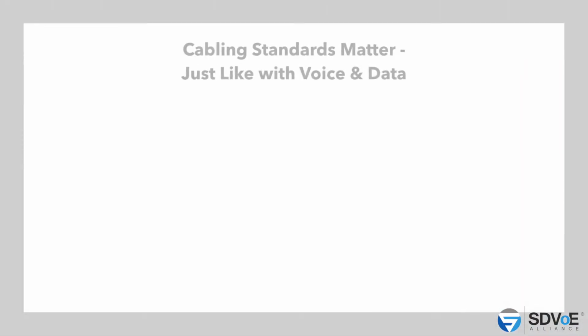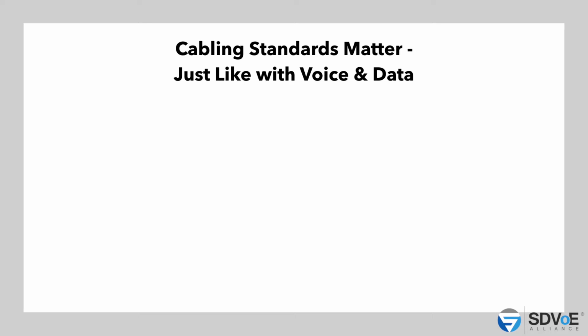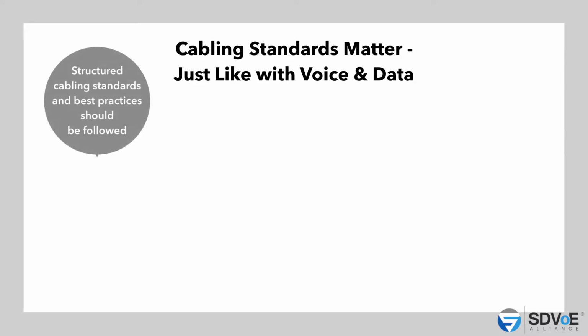So cabling standards. HDBaseT has really got its own standard, but if we start looking at the networking world and we start thinking about voice and data and any other type of application that we're now able to deliver over a cabling system, we're actually governed by technical standards. So in Europe we have EN 50174. It's a generic cabling standard that every cable installer fully understands. We've also then got our local country codes, and then we've got our international codes. So these actually tell us how we're going to design, how we're going to deliver that cabling plant, which is going to be able to support that AV system.